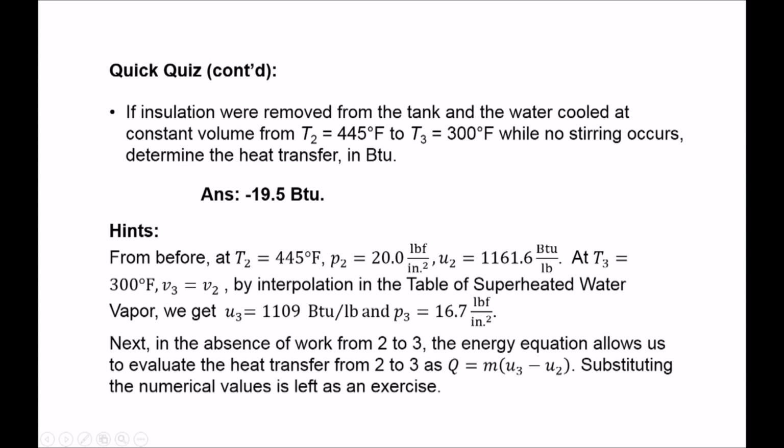Next, in the absence of work from 2 to 3, the energy equation allows us to evaluate the heat transfer from 2 to 3 as Q equals m times (small u sub 3 minus small u sub 2). Evaluating the expression numerically is left as an exercise.